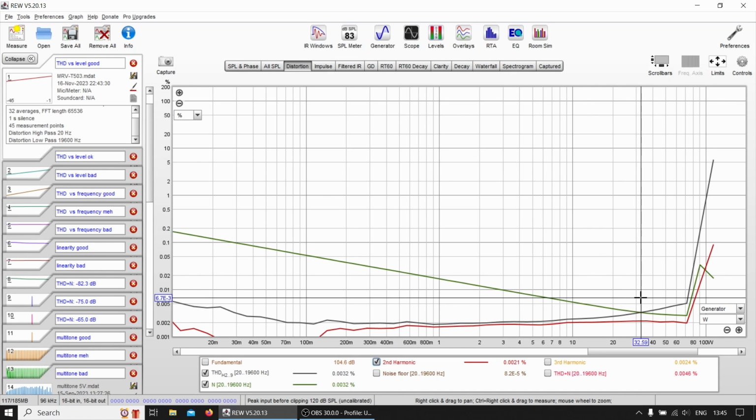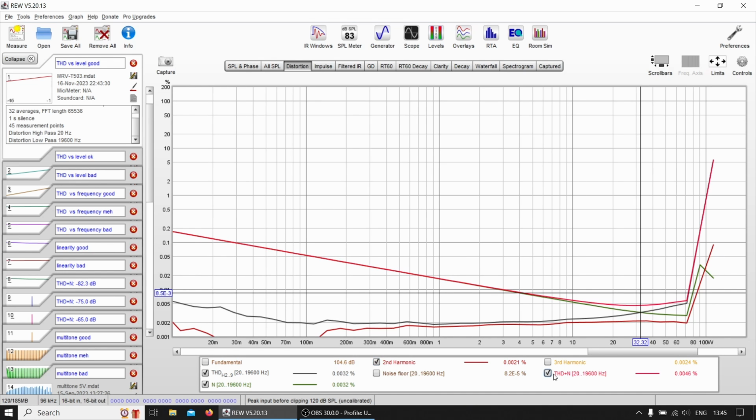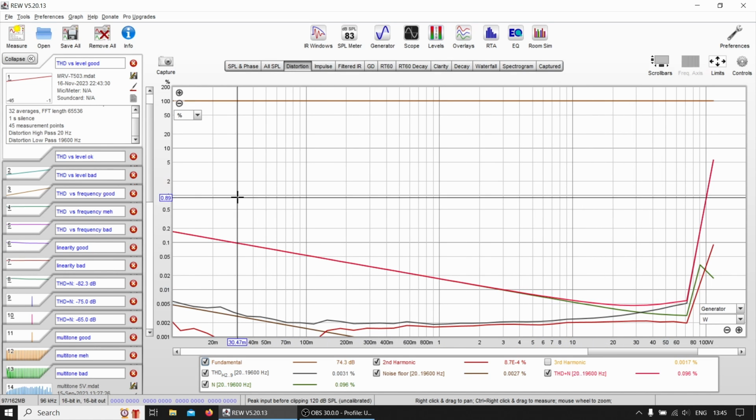And this is kind of a crossing point where THD overtakes the noise. THD plus noise is the actual sum of all the components of everything. Now, if we have a look at the percentage, everybody talks about the rated power. Amplifiers are usually rated at 1% THD plus noise, so at this point.